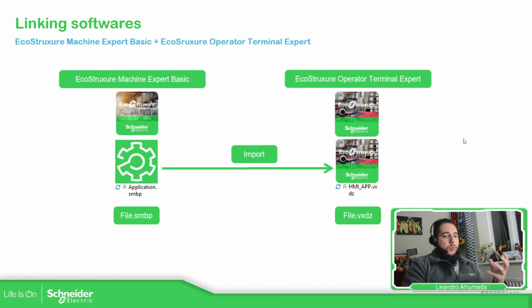In order to link the variables from the PLC into the HMI, we have the option to import the project that we have in EcoStruxure Machine Expert Basic into the EcoStruxure Operator Terminal Expert, so we can easily identify the variables with the same name and much simpler.